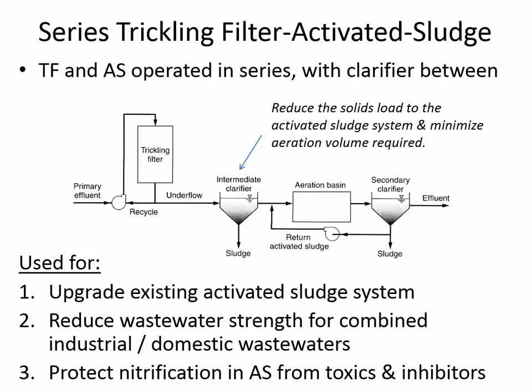If you're settling out the sludge and removing it, anything that was contaminating the sludge, like the type of industrial discharges that could cause damage to nitrifiers, matters, because nitrifiers are really weak bacteria and they're very sensitive to inhibiting substances. And so by removing this sludge, instead of letting it get into the aeration basin, you're sort of protecting what's living in the aeration basin, including if you have a nitrification step going in there.